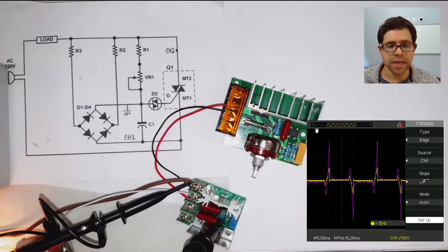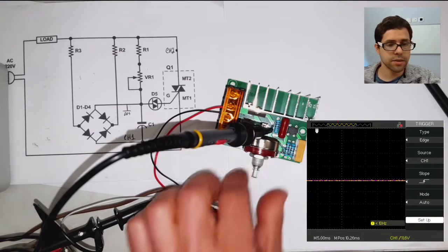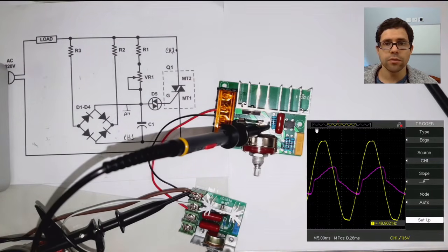So now let's see what is the difference in this improved circuit that we just covered. I just swapped over the probes of the oscilloscope to measure the voltage across this second diode, and now I'm going to turn on the supply voltage, and look what happens. All of a sudden you can see that we no longer have an RC circuit with this phase shift. Now we have this strange waveform. Here we see that the voltage reaches 0, and my capacitor will start to charge from that point, which is very much the ideal condition.